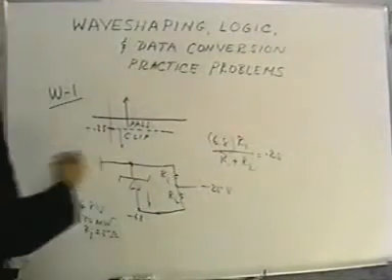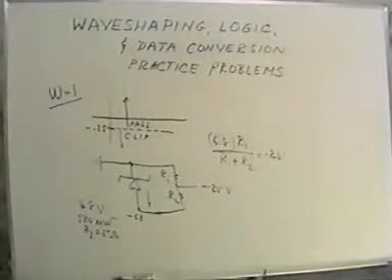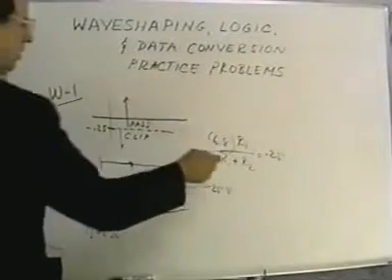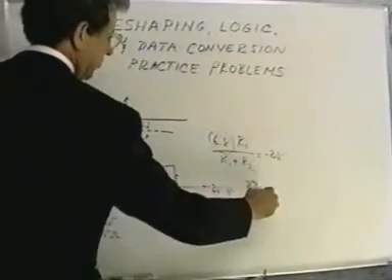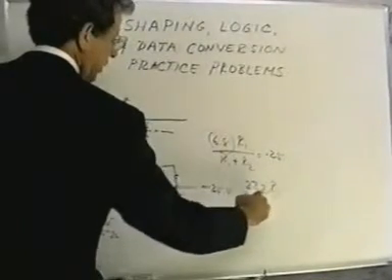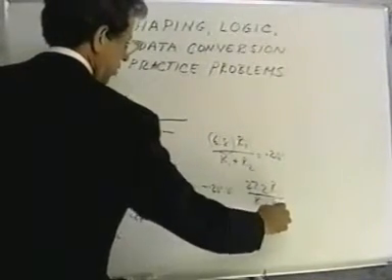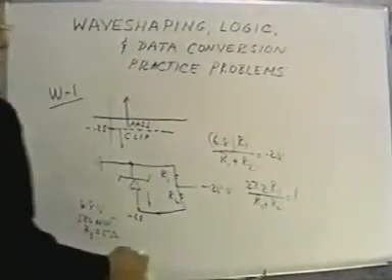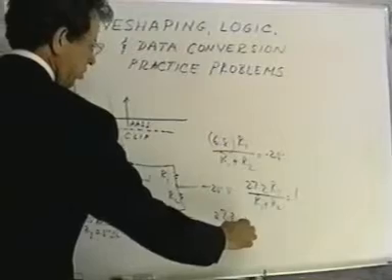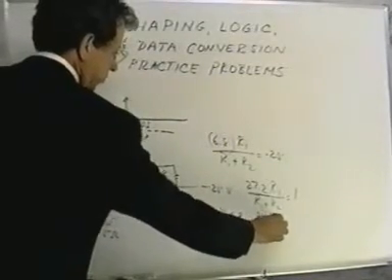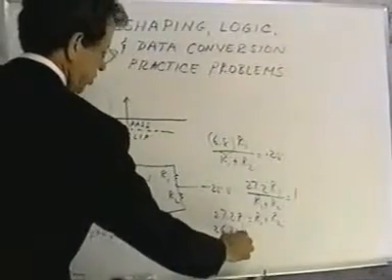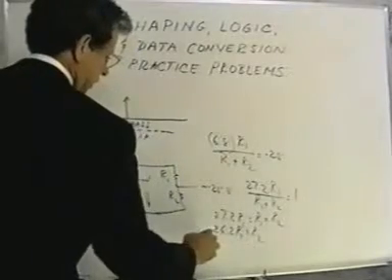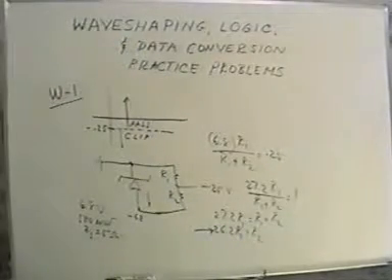So from this equation, I have really two unknowns, R1 and R2, so it's not possible to solve for both of those. But if I proceed, first of all, if I multiply both sides through by 4, I have on the left-hand side 27.2 times R1 over R1 plus R2 is equal to 1. So that 27.2 R1 is equal to R1 plus R2. 26.2 R1 is equal to R2. Well, that's as close as I will get to a mathematical solution.